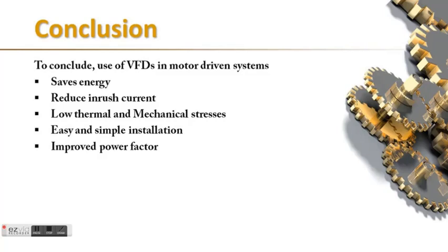VFD as a starter increases the lifetime of the motor. At the time of starting, lower voltage and frequency are supplied to the motor so that it draws less current. Thus, VFD protects motor windings and its components from any damage due to large current. VFD also decreases the thermal and mechanical stresses on the motor, thus increasing the lifespan of components such as belt, chain, and gearbox connected with the motor-driven system.